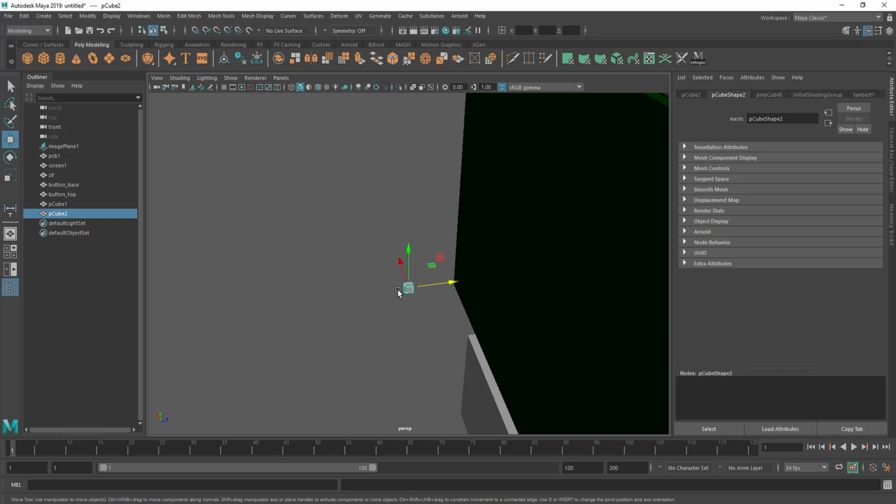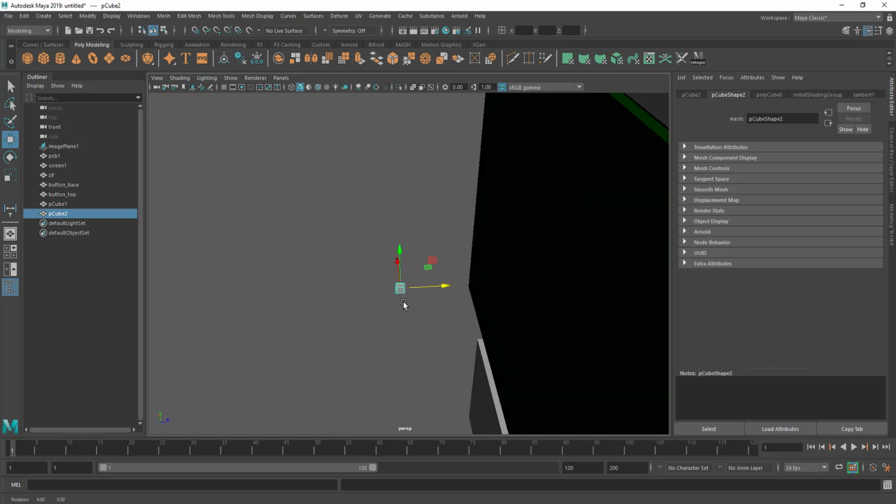Now when it comes to 3D printing, the thickness of a material is obviously extremely important to its rigidity, as would be what you're printing the material out of. I'm not going to go into all of that in any great detail. I'm just going to say through my own experiments with an FDM printer, with both PLA and PETG materials, about 2 millimeters is quite rigid enough for this sort of case. Your mileage may vary, so you can make it as thick or as thin as you want. Maybe you want something that prints faster but just doesn't have the robustness. That's also quite fine. The only measurement that's critical on this is the thickness.